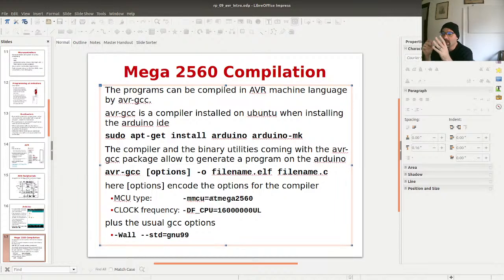In particular, we need to add information to this ELF file specifying, for instance, what we want to write on the EEPROM when the microcontroller is written, or specifying, physically, since the bootloader is a very stupid program, from which flash location we want the program to start to be uploaded, and so on and so forth. So this is typically done by another program.